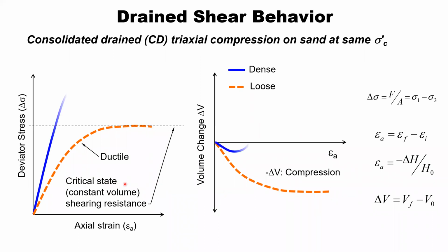When we talk about dense soil behavior, we can use our knuckles again as the analogy. We're going to start with the case where you've already got your knuckles packed closely together. That is, you've already got the knuckles in the open spaces that loose sand fell into. Now, if we shear in this case, what happens is, as you see here, my knuckles have to ride up and over one another in order to start shearing.